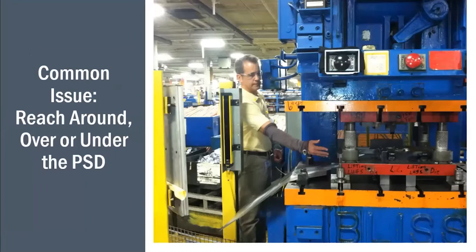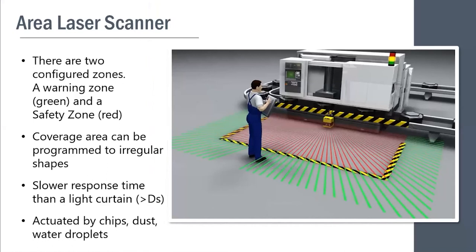Common issues with presence sensing devices: we go back to reaching around, over, or under. You're not going to generally go through a presence sensing device like a light curtain, but here's a case we saw before, with the field in front of the press, where we can reach around it from the side. Area laser scanners have become very popular. They're great, flexible devices, relatively inexpensive, to provide a nice safety zone.